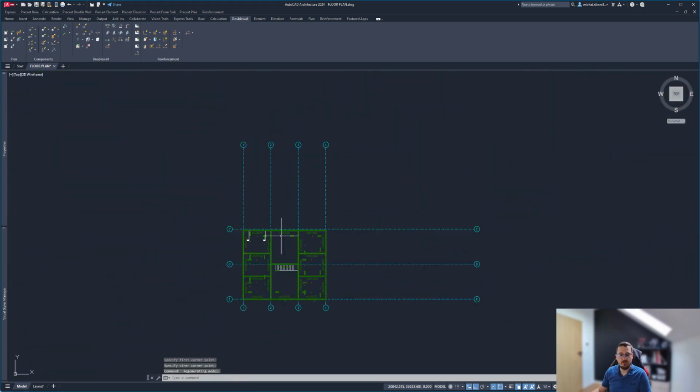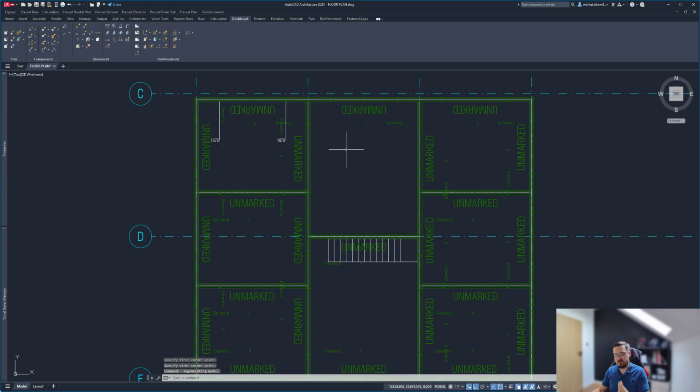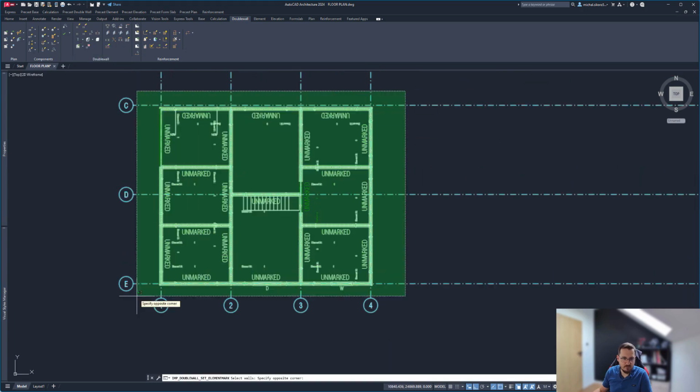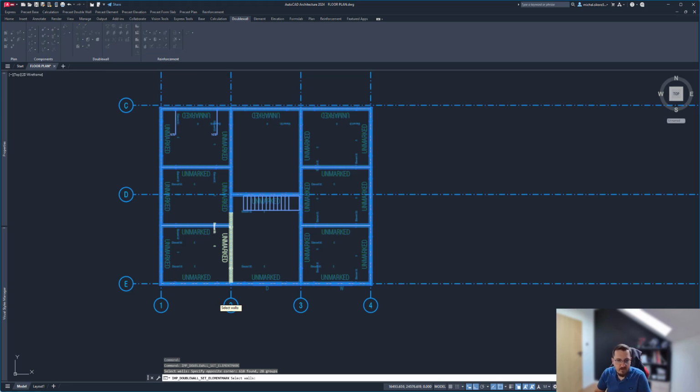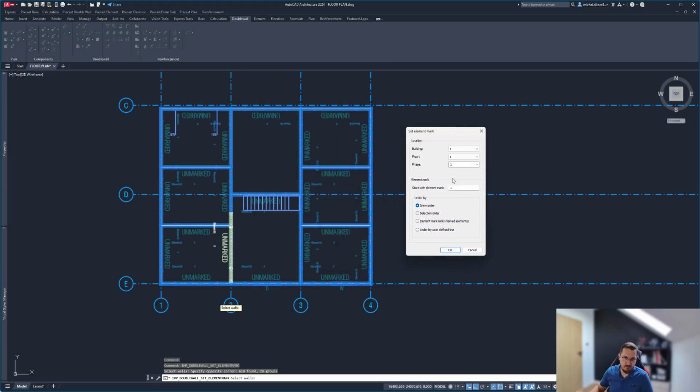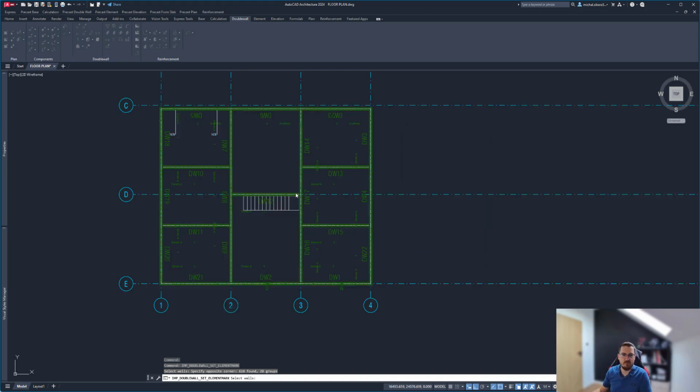So how do you now actually get drawings out of it or save it? Because all the elements are unmarked. The process is a bit different than with other elements in Impact. We actually have to set the marks manually for our elements. So I'm going to select the walls. That works for double walls. With that, the double walls will be saved with a prefix that we have set in the element settings. I start with the element mark. It can be 1, draw order or selection order. That determines what numbering order is placed upon the elements. And as you can see, we have different wall types.